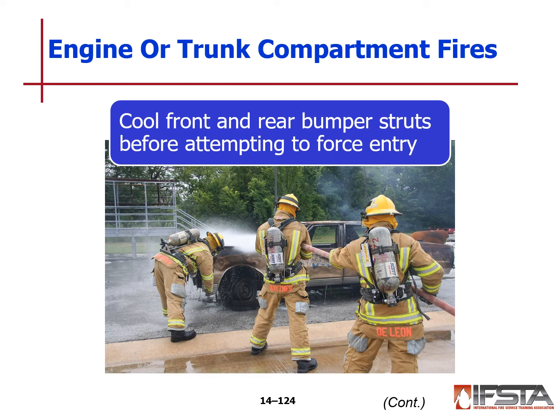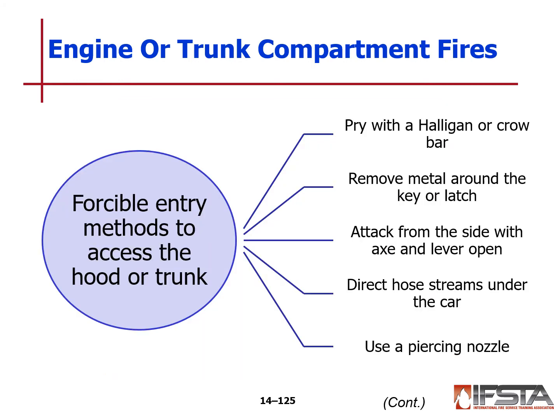We want to, again, keep in mind if you're at the front and rear bumper struts, attack or approach at that 45-degree angle. Remember where your safe zones are. You don't want to end up directly in front of it. If you do, you only want to be there for a limited amount of time. And we can work to get the hood up. Hoods can be problematic.